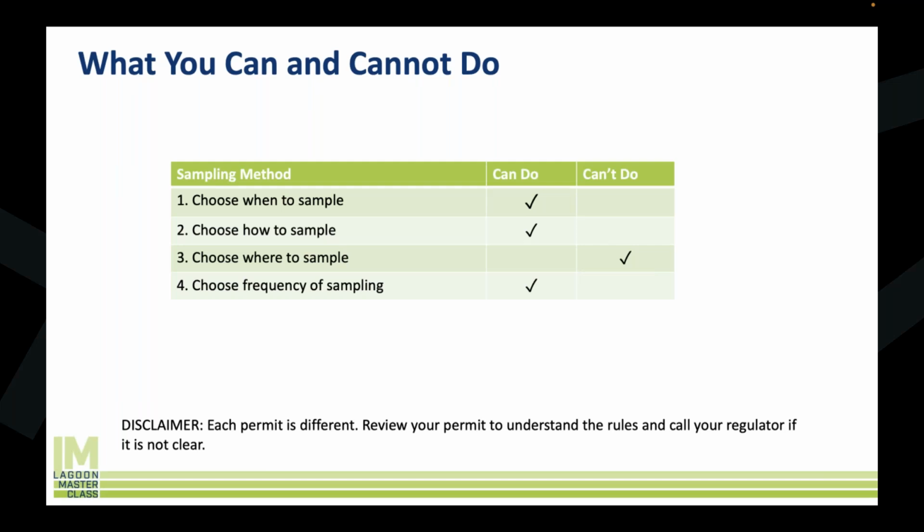Now, I've never heard of a DNR requiring that for a lagoon system, or for any system, to be honest with you, but maybe it does exist for larger systems. And it's not practical, and it's not feasible in a lot of these cases. But on the flip side of that, taking one grab sample a month using that as your 30-day average is not an average of anything. That's just one sample on the day that you took it.